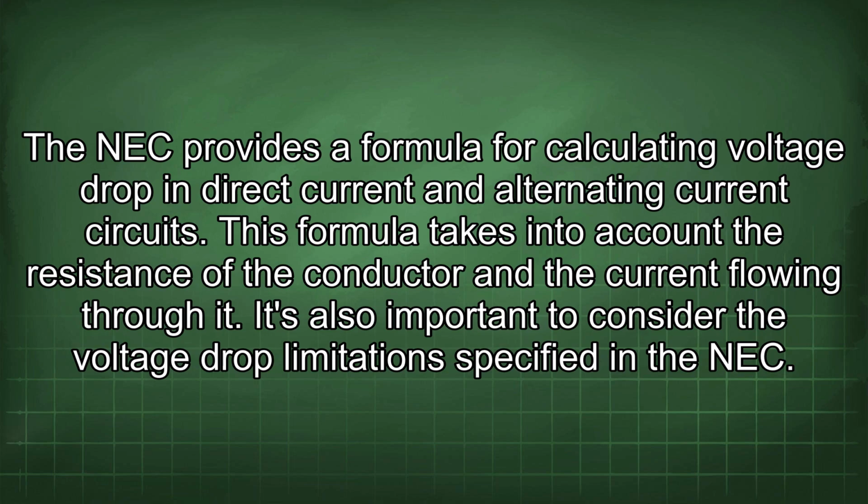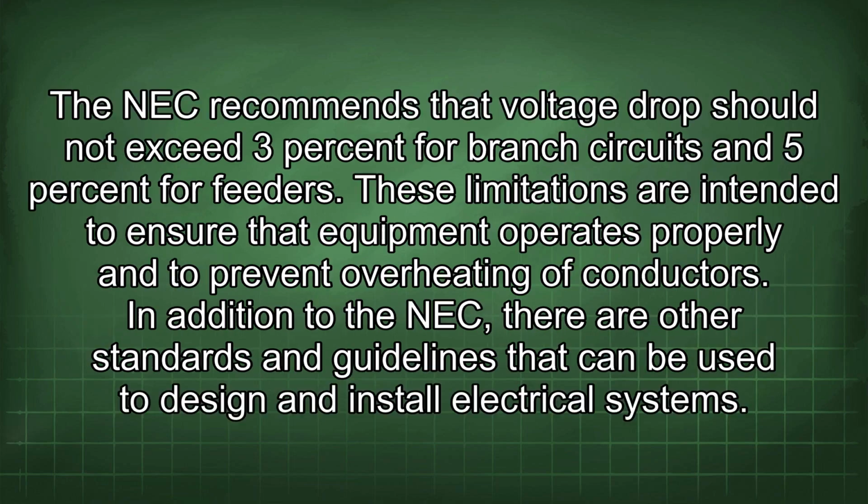It's also important to consider the voltage drop limitation specified in the NEC. The NEC recommends that voltage drop should not exceed 3% for branch circuits and 5% for feeders. These limitations are intended to ensure that equipment operates properly and to prevent overheating of conductors.